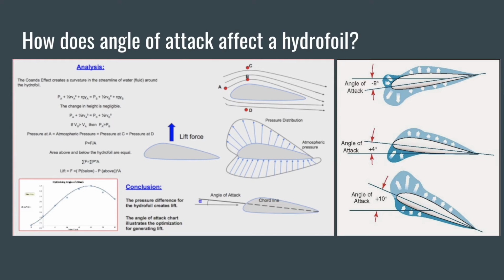The angle of attack is defined as the angle between the free stream air and the chord line connecting the leading edge and the trailing edge. For most cases, increasing the angle of attack increases the coefficient of lift. There is, however, a critical angle where the coefficient of lift becomes a maximum and an increase in lift is no longer possible. This creates separation of the airflow from the airfoil and can be thought of as an aerodynamic stall, causing no lift generation and a large drag force on the airfoil.